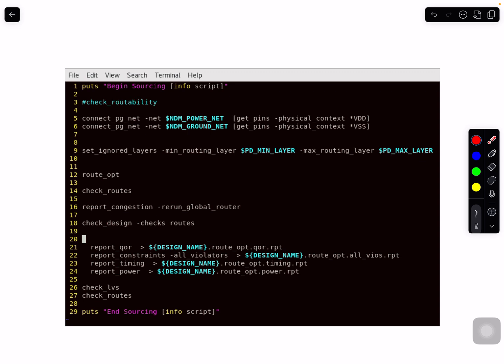But before you do the routing, what do you need? Think about it. Of course, you need a netlist, with standard cells and macros there, all linked, meaning they are able to get their layout views. You open a design. Before this, what was the stage we ran? CTS, right? So basically, you first want to check if every cell is placed, even CTS cells, even non-CTS cells, and whether all of them have a legal location or not. That's one thing. The second thing is whether you have done CTS on it or not.